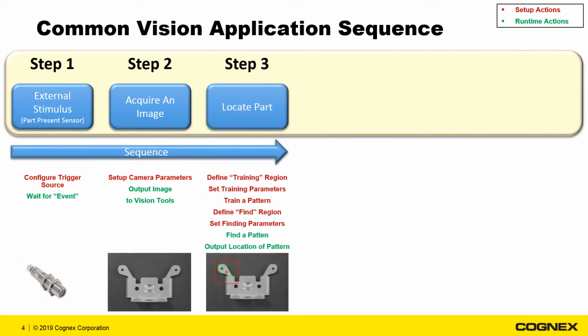Most applications start by locating the position of a workpiece in the image. This step is useful since it can reduce the complexity and cost of hard tooling to orientate and present the part in a fixed location. Once we locate the part, we can provide the location information to subsequent vision tools so they can automatically adapt to the position of the part. We call this fixturing.